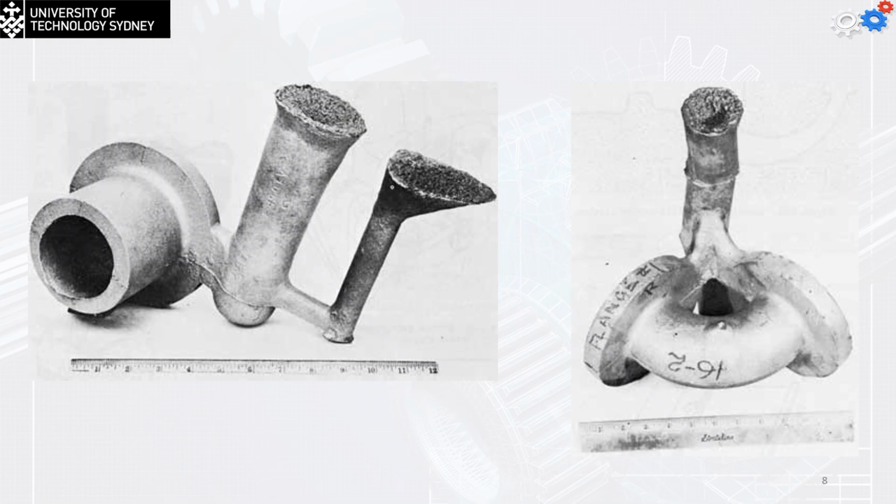So this is the casting part. As you can see, this will be the runner and the riser, and this part will be cut off, and this part will be the casting part. The runner and riser can be remelted and reused. That's another example, for making an angle pipe.